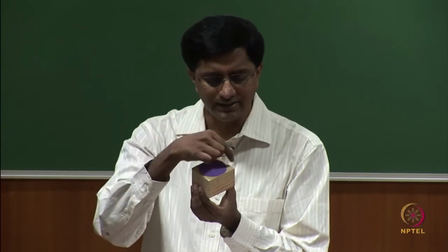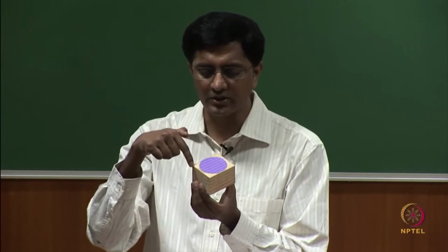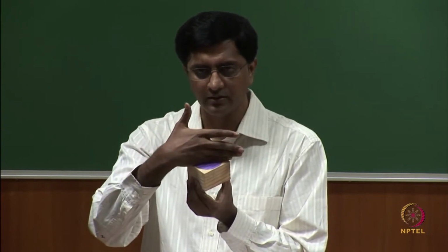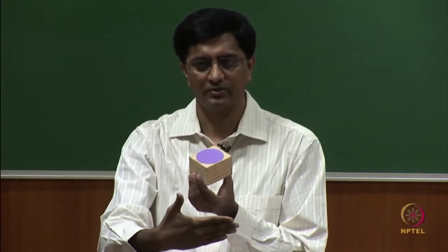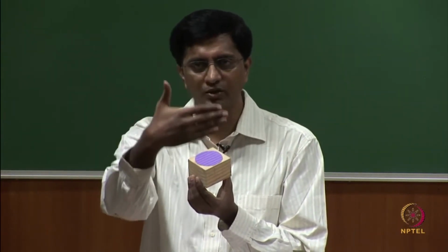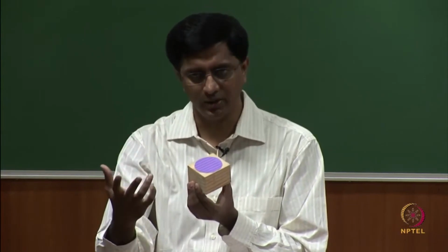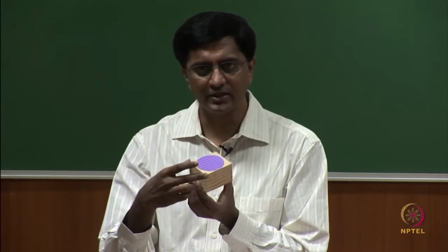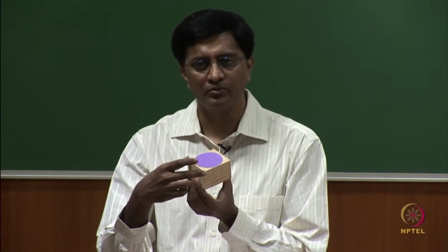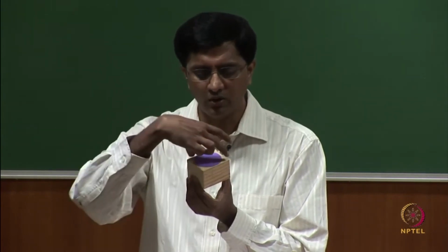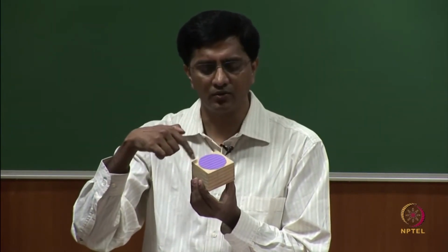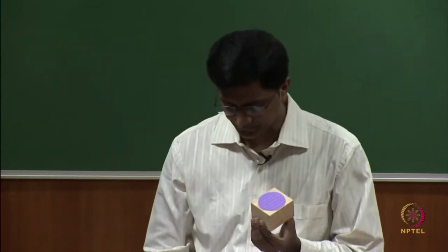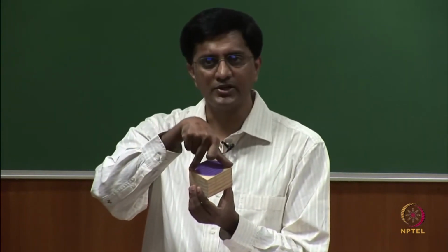If you look carefully, this diagonal from this corner to the other corner on the top face is parallel to the projection plane. So, since this line is parallel to the projection plane, it captures the true length. Now, a simple question in geometry. Let us say the side of the cube is of unit 1. What will be this diagonal? This diagonal will be of length square root of 2. We know this from trigonometry. So, this is captured as true length.